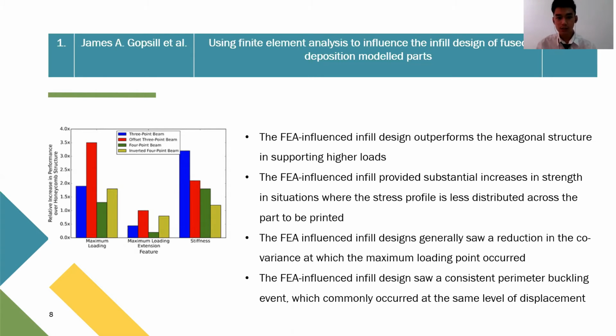The result: we can confirm that using finite element analysis, the influenced infill design outperforms the hexagonal structure in supporting higher loads. Number 2, the finite element analysis influenced infill provided substantial increases in strength in situations where the stress profile is less distributed across the part to be printed.